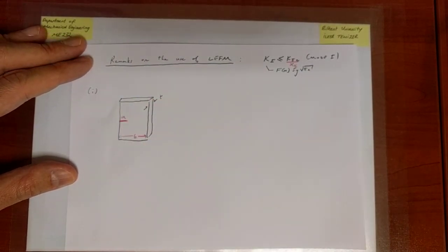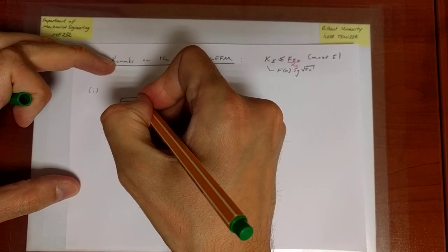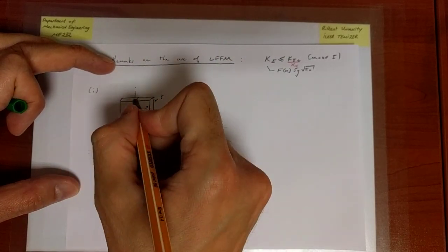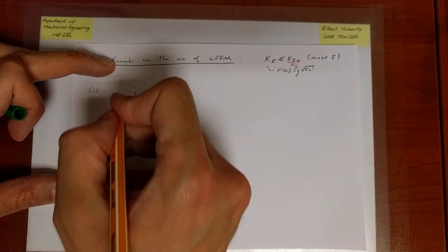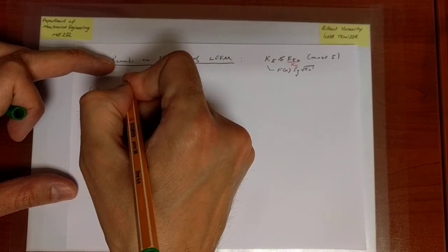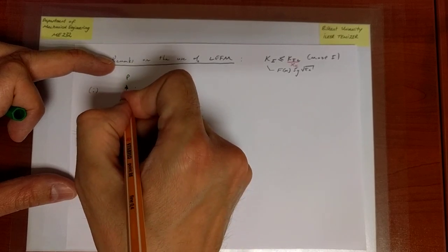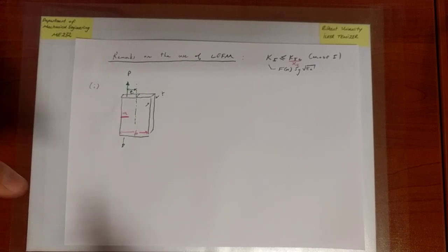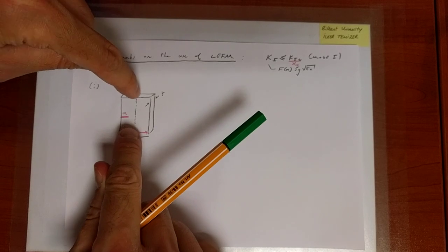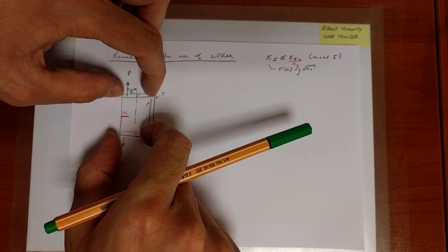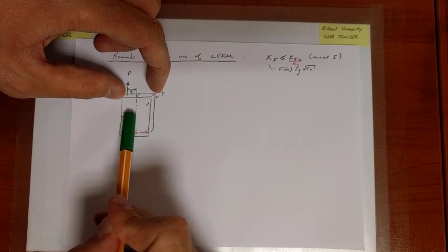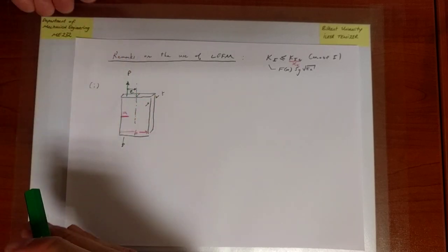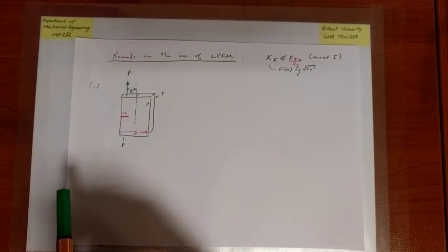And we're going to load it. But as we load it, let's take the central axis, so that would be sort of the central plane. We're not going to load it through the center. We're going to load it with some offset. So that's where we are going to apply the load, and that offset is through some amount, let's say E. Now, what we've assumed intrinsically so far is that this load is applied right through the middle, so that the state of stress, or the equivalent representation of this loading on the cross section where the crack is present, is just loading. It will give rise to a uniform stress field, etc., if the crack is not there, of course.